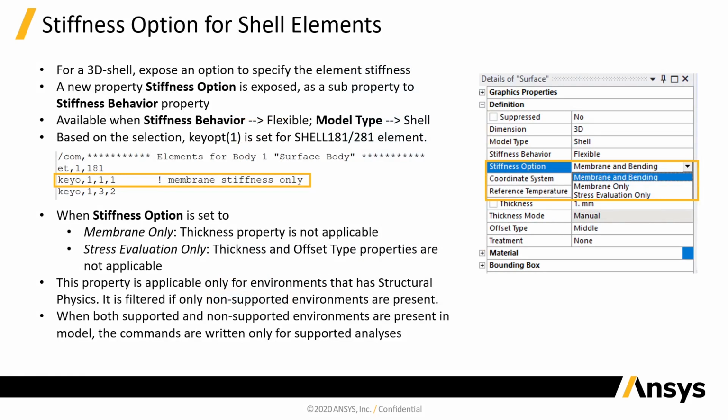Staying with shell elements, I mean, you may know shell elements, they typically have bending and membrane behavior, so they are used for thin-walled bodies, and they're two-dimensional surfaces which have rotational bending stiffness as well. So that makes them really powerful to model thin-walled bodies like cars and planes and trains, etc.